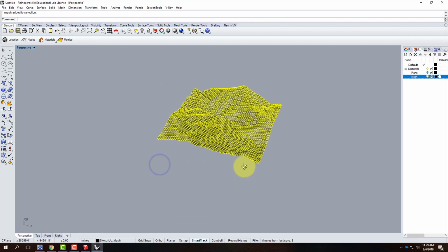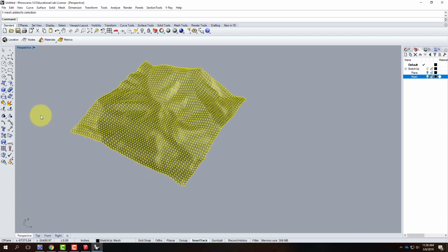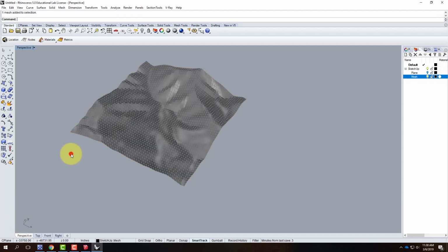For clarity purposes, I'm going to orbit around so that I'm facing in my x direction here and my y direction there. I'm looking at my little axes down here at the bottom, so that I can orient myself. Does it really matter whether you're in the x or the y or not? No, but I just want to be going in two different directions. Remember when we did curved networks, we distinctly wanted curves going in one direction and curves going in the other direction. So using the axes to help doesn't hurt.